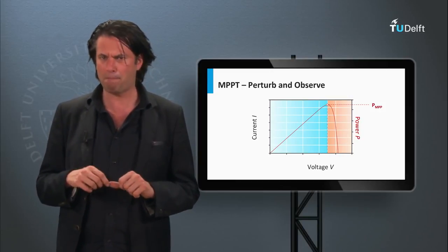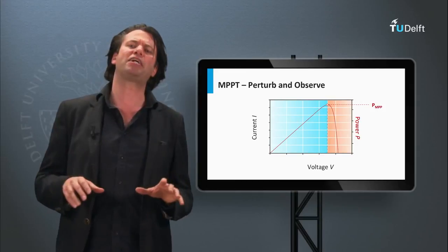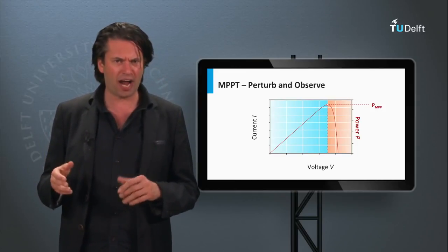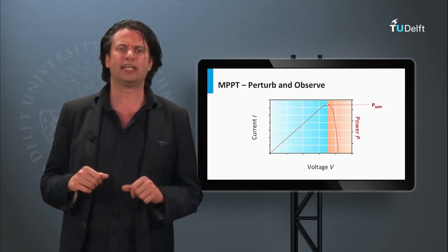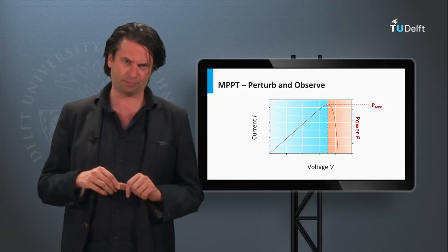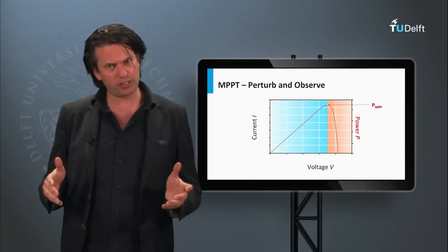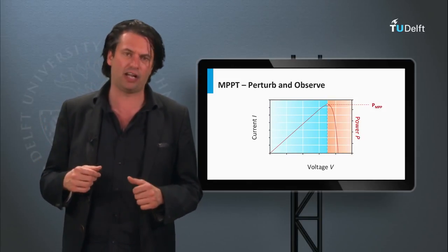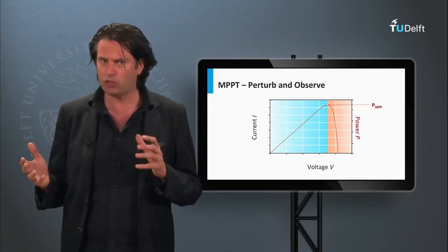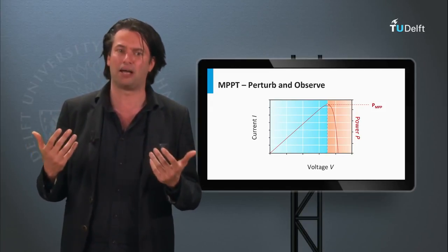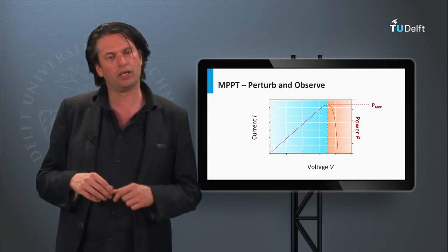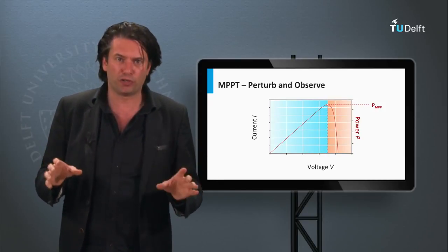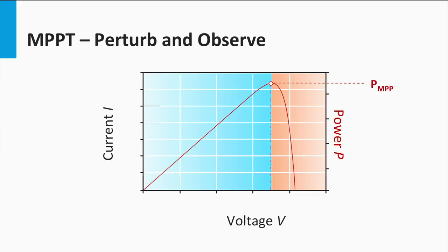This kind of maximum power point tracking involves direct measurements of current, voltage or power, and a more accurate, faster response than the indirect method. Due to time constraints, we shall look at a couple of the most popular kinds of algorithms, which are sometimes also classified as hill climbing algorithms. We start first with the perturb and observe, or P&O, algorithm.